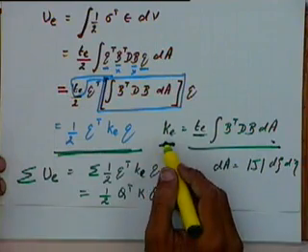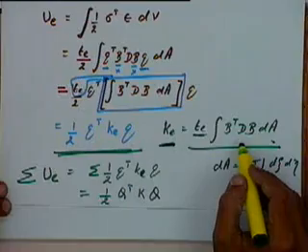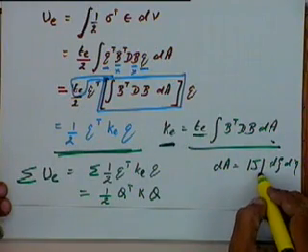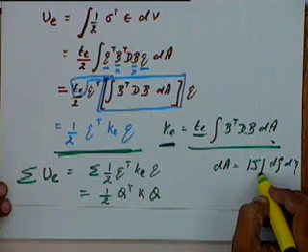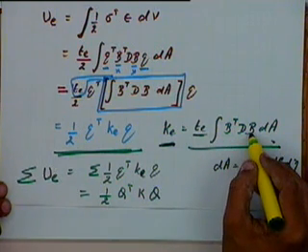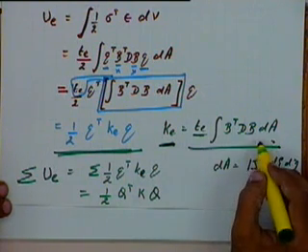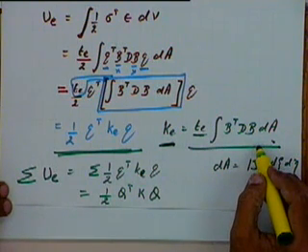So unlike our 3-noded elements and all our one-dimensional elements, in this case for finding out the stiffness matrix, we have to carry out this integration. And this integral is going to be quite complex, because we will have the term of the Jacobian, which also contains zeta and eta, and B transpose also contains terms in zeta and eta. So the whole thing is going to be quite complex. Any questions up to this point?